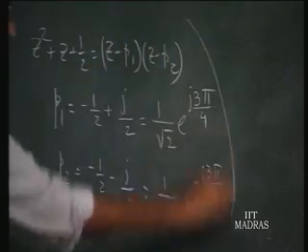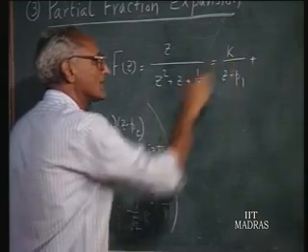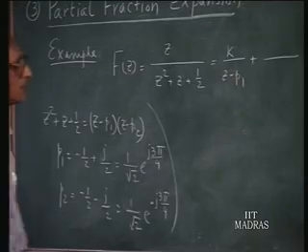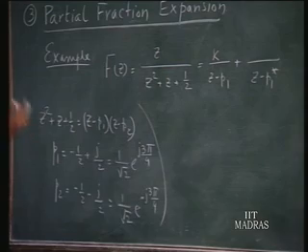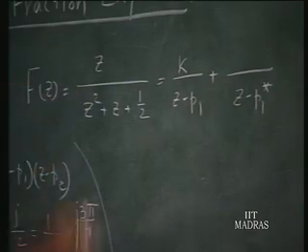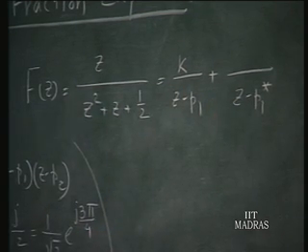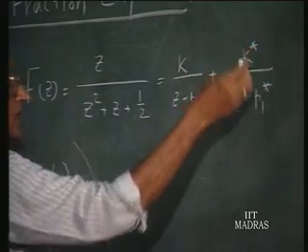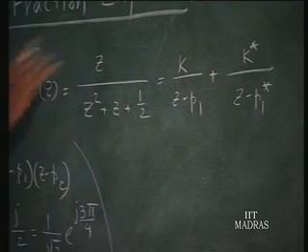So suppose I write this as k upon (z minus p1), then since again all the coefficients involved here are real, this will be (z minus p1 conjugate). So p2 you don't have to write separately. If it's p1, the other has got to be p1 conjugate, because there are only two poles, and if one is a complex pole, it must be accompanied by its conjugate. Therefore, it goes without saying that the other pole must be p1 conjugate. Not only that, if the residue here is k, the residue associated with this must be k star. Then only when you have a common denominator and work it out, you will have numerator coefficients all real, as it is in this case.